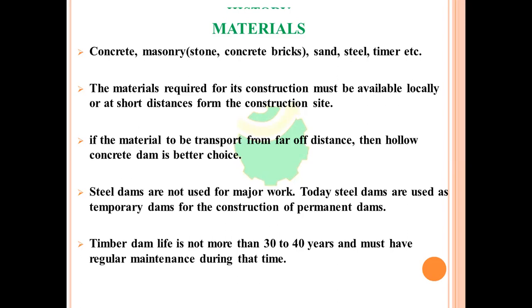We must take care that the materials are available locally or surrounding the reservoir site because it decreases the distance and cost of construction. If the material is to be transported from a far off distance, then hollow concrete dam is a better choice. If there is no chance of availability of materials near the site, then we must prefer hollow concrete dams. Otherwise, gravity dams. Steel dams are not used for major works.